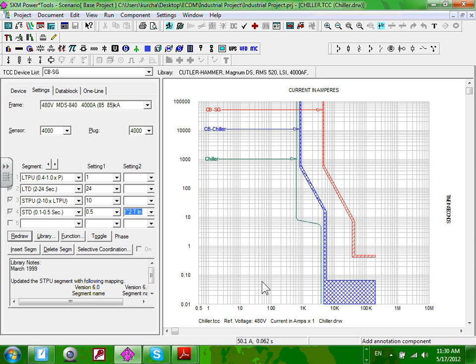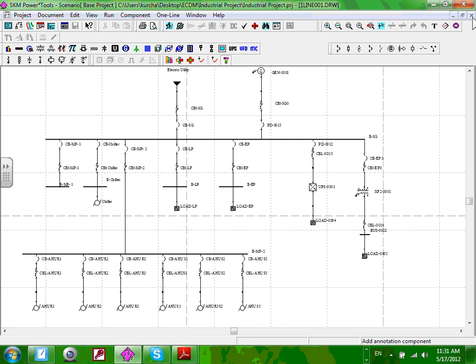But my point is, guys, you can run all these. It doesn't matter what the outcome is. What matters is the process. I know how to run it now. Moving on, you're going to spend some good time making sure your one-line diagram is right, the voltage is right, the length is right, the feeder is right. But the process is the same. If I put a feeder, guys, as 500 and it's supposed to be, say, 300, it will give me some data. It's not the right data, but you know how to change it. Go to your calculation, change it to 300 or 500, whatever it is.